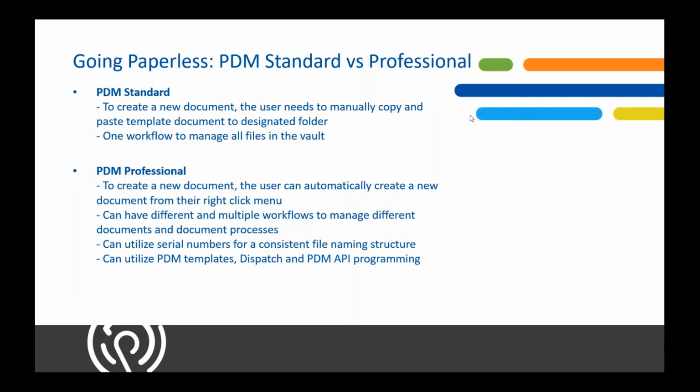From there, the user can just go ahead and do the normal operations of filling out the data card, filling out the form, saving, checking in, and using the workflow to manage that file. Keep in mind, in PDM Standard, you're limited to one workflow. So that one workflow has to manage all your files in the vault.